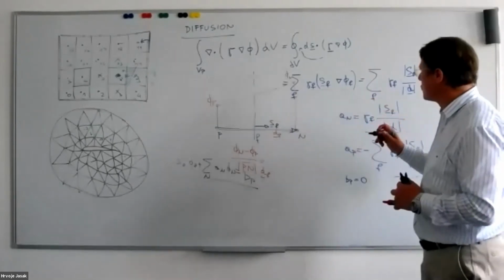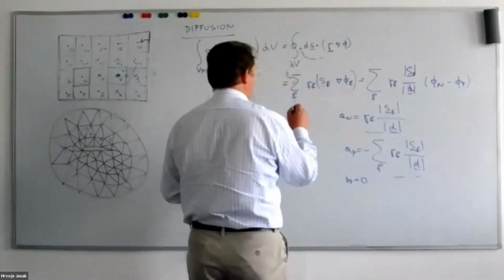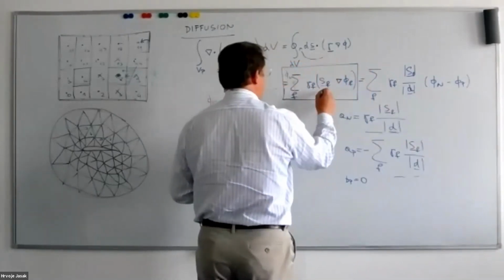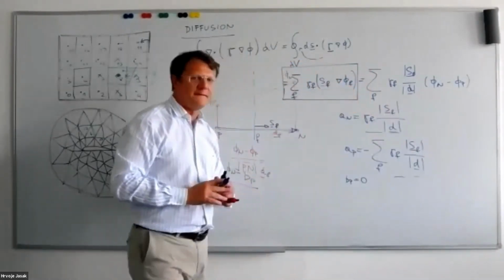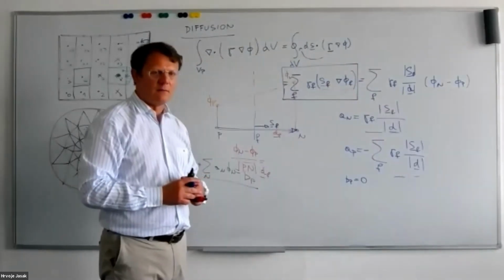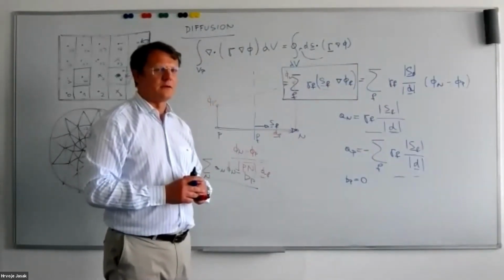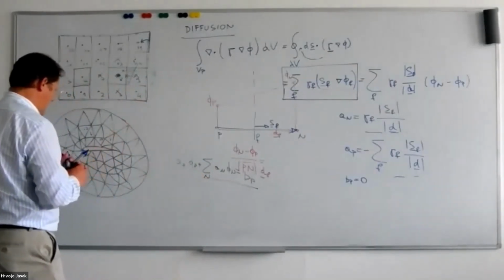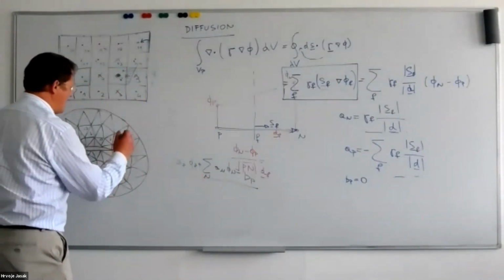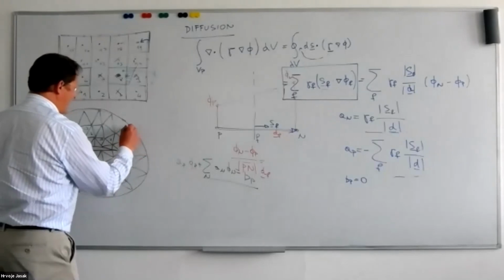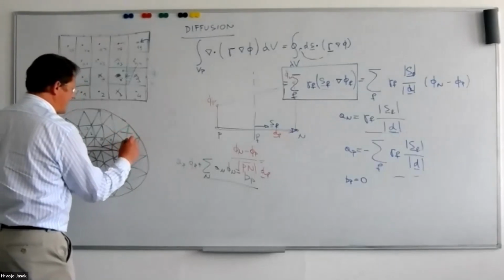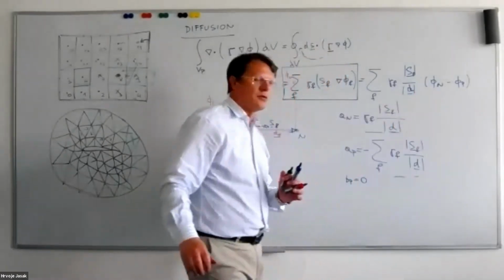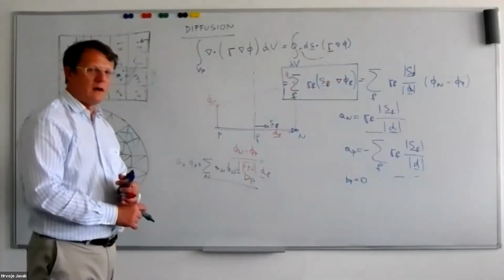What I have shown you so far is that the diffusion operator defines S f dot grad phi f as the integrand term over all faces. Therefore, if I pick a cell which is next to a boundary, like this one, for those two faces, I will use the standard discretization procedure as we did so far.